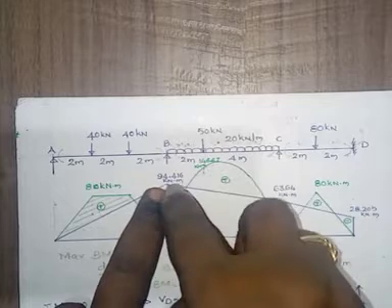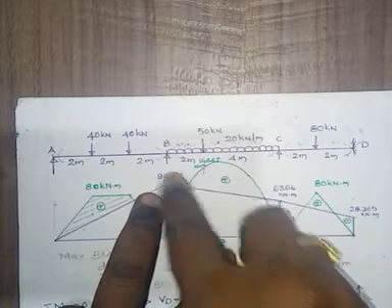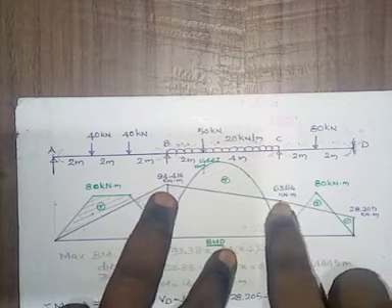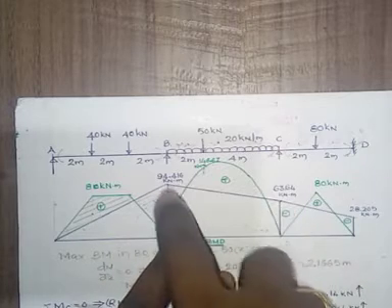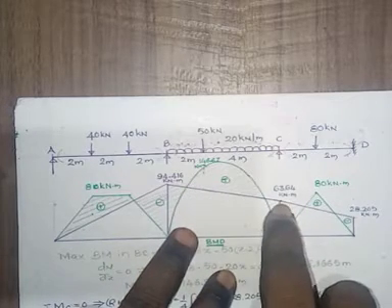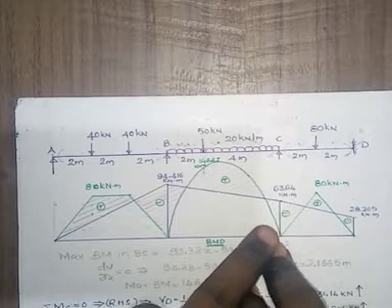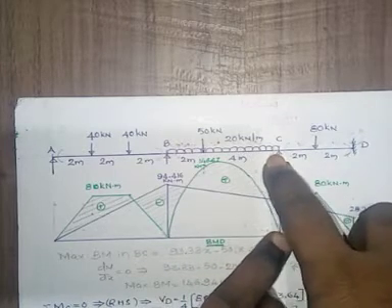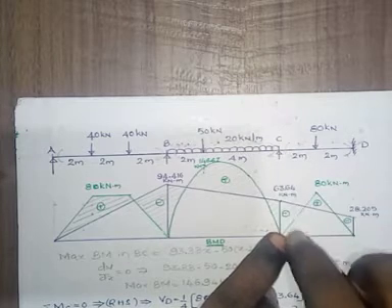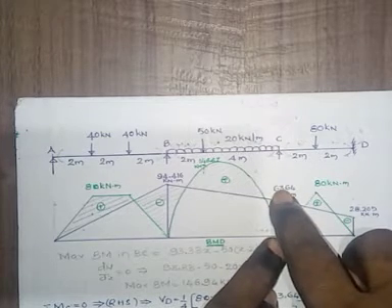Then here we have already shown the hogging moment above the reference line. This one is 63.64. Draw the ordinate and then join the two ordinates by a straight line. Here this is the support moment diagram in span BC. Then for CD, this one is already drawn, 63.64.